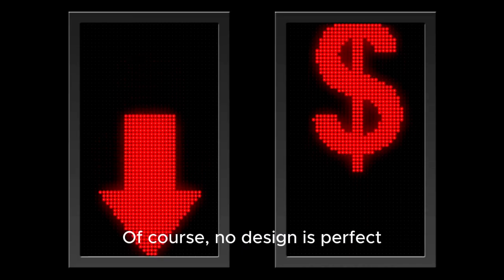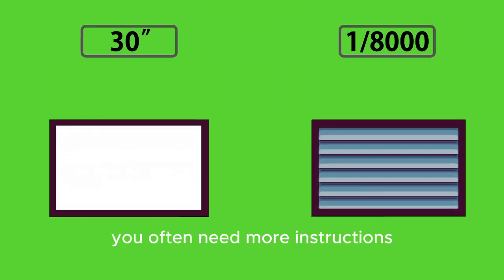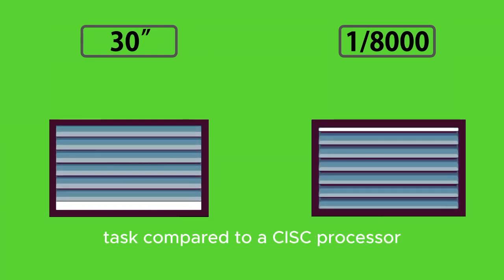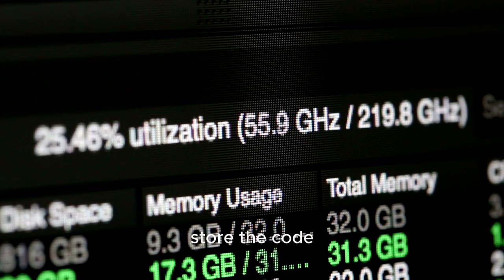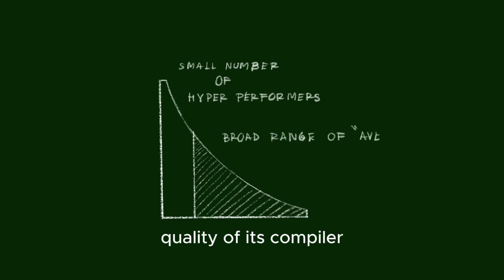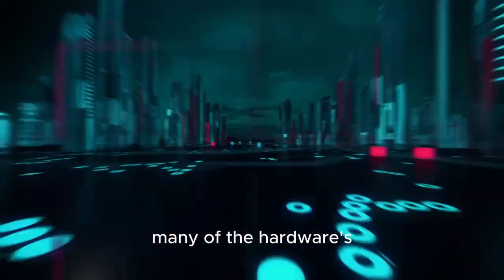Of course, no design is perfect. RISC does have some limitations. Because each instruction does less work, you often need more instructions to accomplish a complex task compared to a CISC processor. This can lead to larger program sizes, which means more memory is needed to store the code. And the performance of a RISC system is heavily reliant on the quality of its compiler. A poorly optimized compiler can generate inefficient code that negates many of the hardware's advantages.